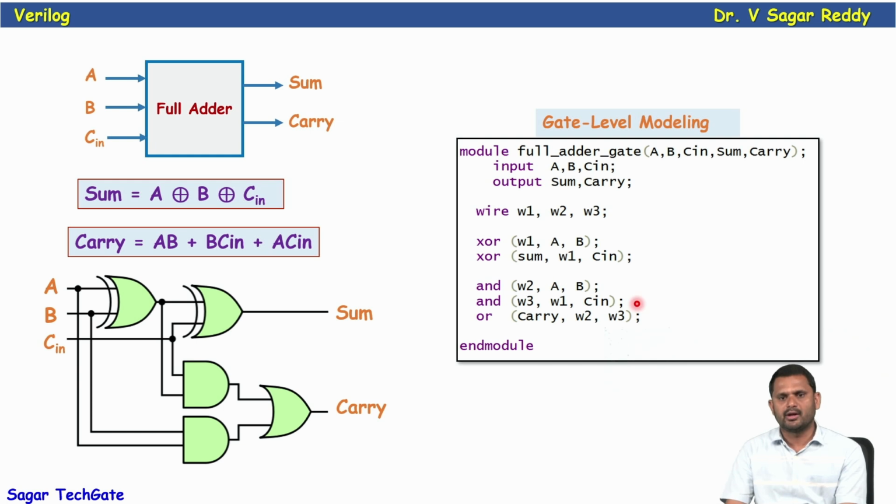In gate level modeling, now see here, module name, ports declared as input and output. These are the intermediate signals we use to connect different entities in our system. We already discussed the wire concept in detail in the Verilog data types video; if not, please visit that video. Right now, see here, we describe the full adder in terms of primitive gates.